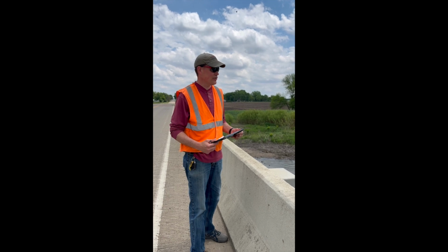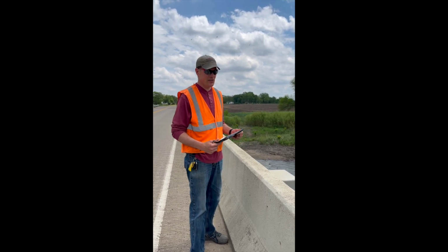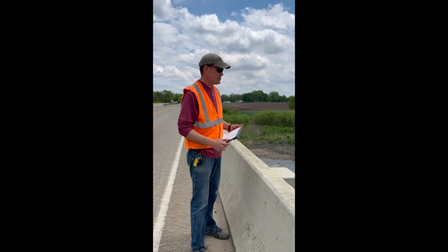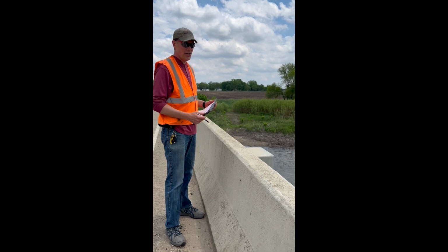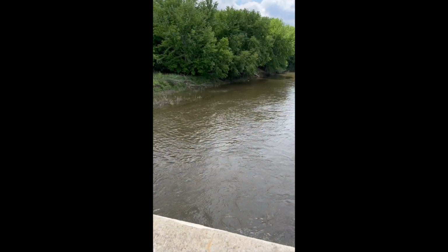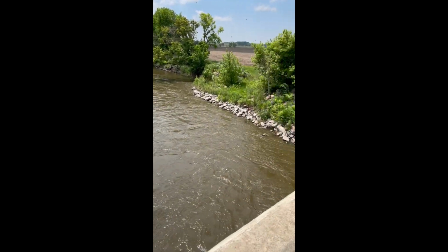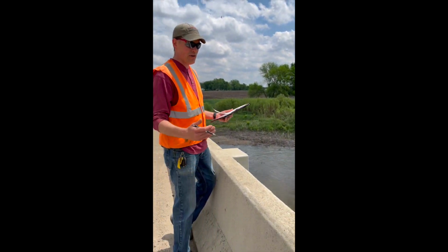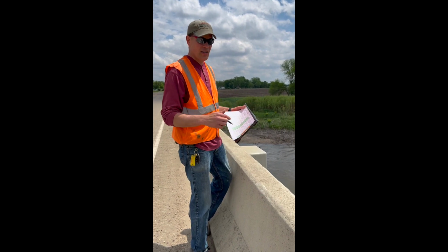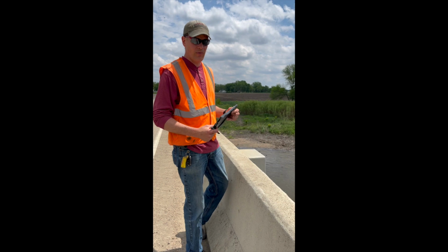We're on the Trent site for the Big Sioux, and we're going to be taking a discharge here. This is typically what we'll do here, is take a discharge at our location, but this one has a lot of turbulent water on the right bank side that makes it difficult to get a discharge, especially with the rocks and stuff being under there that the radar doesn't know what it's looking at in the profile.